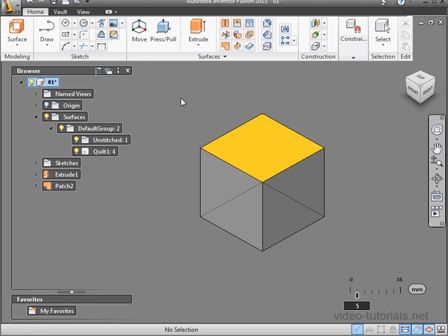You've probably noticed here that one side of the surface is yellow and the other is gray. The gray indicates positive and the yellow negative. The designation of positive and negative has to do with how Inventor Fusion stitches the surfaces together. For the program, it's easier this way to understand which edge is stitched to which edge, and if gaps exist, and which gaps need to be filled, etc. A yellow surface will generally need to be filled around, so in order to do that, Inventor Fusion provides us with a tool for that.